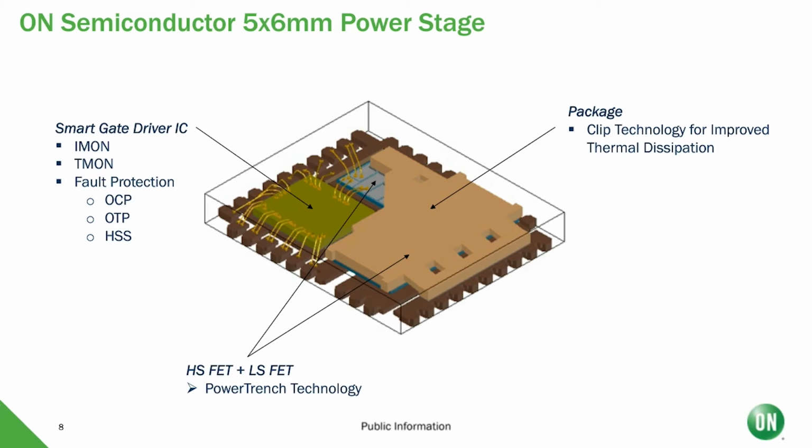And also the current reporting gives the controller a sense of what the total output current is, so that the controller can prevent an overcurrent event. It can perform several functions, either to latch off the output when the current limit is reached, or it can do a hiccup function to continue supplying the current, but not let it exceed the maximum current limit.